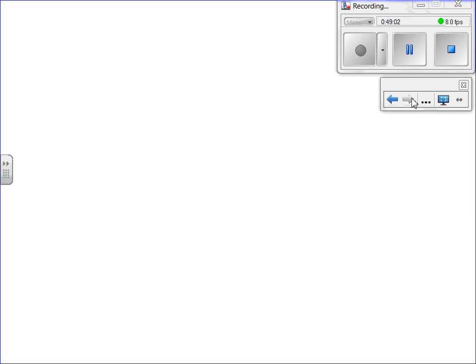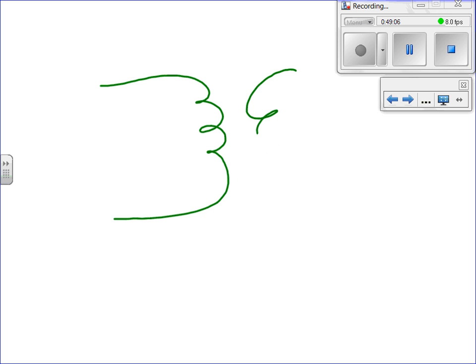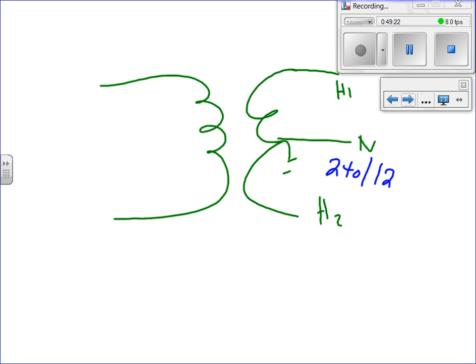I don't want to do the example, I just want to draw that. Here's my transformer. Ground this one. This is hot 1, neutral, hot 2. On this side, this is easy. This is most likely 240/120. How many conductors? Single phase. 3 wire or 3 conductor, right? 3 wire, 3 conductor. On the primary side, you have your fuses here, all this good stuff.